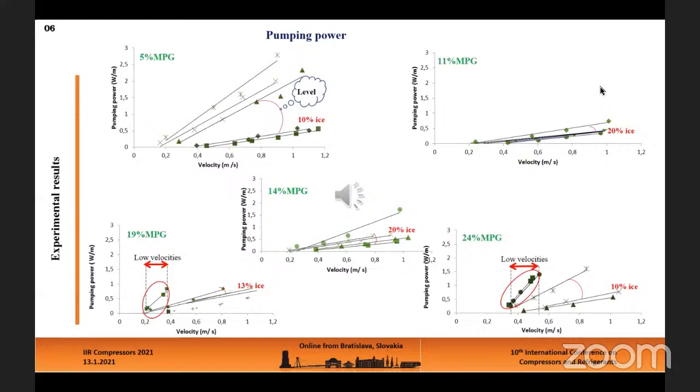This suggests the existence of a local maximum for transport capacity and pumping ratio at a certain velocity. While for the circled curves the pressure drops are very high at low velocity, this can be interpreted by the ice slurry structure and different interparticular forces such as London van der Waals. That's why they have ruled out optimization.